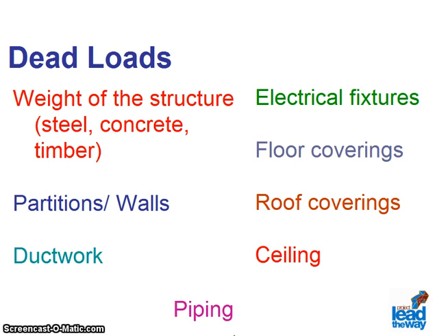Dead loads are gravity loads, since gravity acts downward and is always present. The weight of the structure is considered a dead load, as are partitions, girders, beams, stringers, ductwork, lighting fixtures, plumbing, floor covering, just to name a few. Although dead loads are generally known, many of the details in regard to actual material cannot be made until the design is finalized. Dead loads can be treated as uniformly distributed.